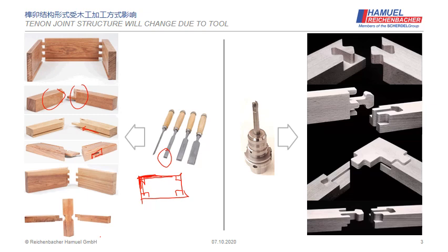But considering if you use this type of tool, which is widely used on the CNC machine, this is a cylinder structure. So in this case, to cut a slot, it's not possible to cut a very sharp edge, but an edge with a radius. So if you use this type of tool to cut a slot, this slot on the 4 points must have a circle on the 4 points.